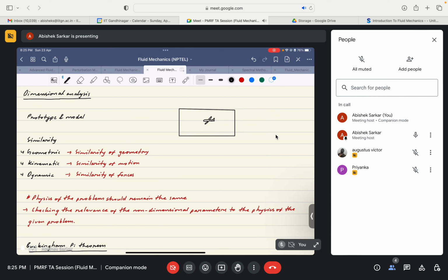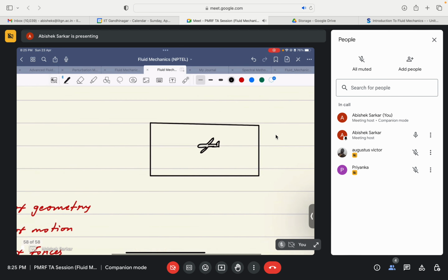Okay, I will zoom it a bit. Okay, so now if you want to see the flow around this plane, the general practice is that we want to see the streak lines, right? As you can remember from the previous sessions, it is the streak lines that we visualize rather than the streamlines. But in a steady flow case, if we assume the flow to be steady, the path lines and the streak lines, the path lines and the streamlines are similar, right?